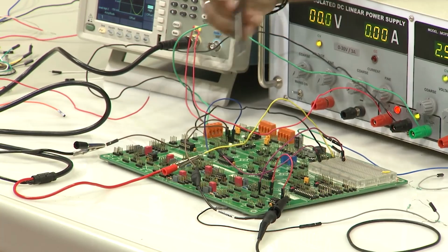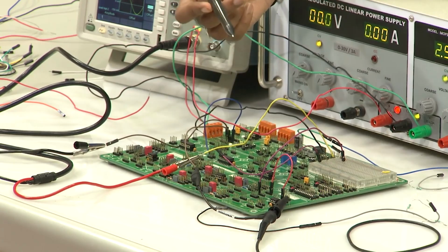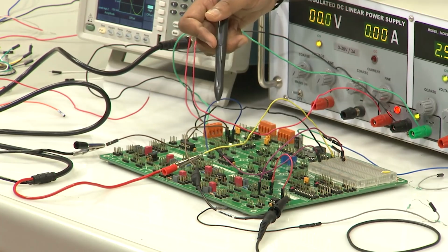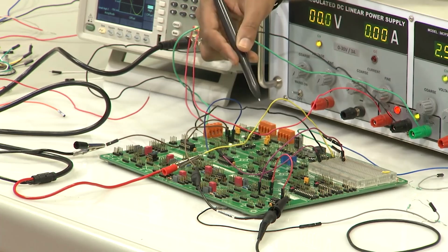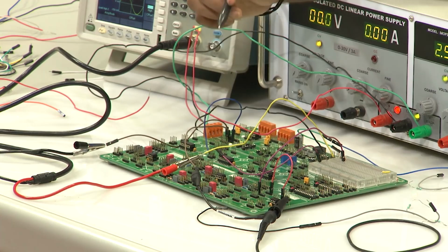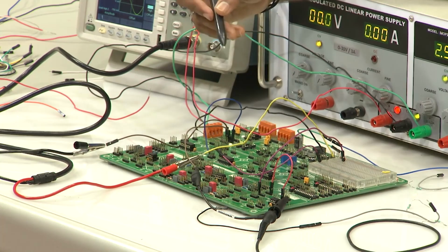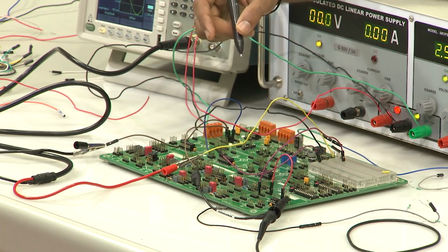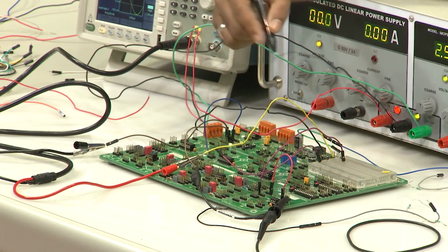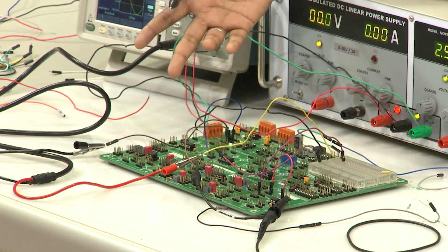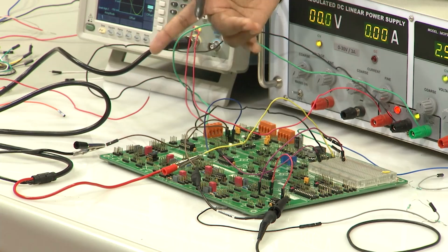For that we need to use the op amp in its non-inverting configuration. Why? Because from the circuit design point of view, we connect the output back to the input. We need negative feedback, right. If it is positive feedback, the output will simply saturate or oscillate. So, we connect the output back to the inverting input terminal. So, what is your R2 resistance then? Then your R2 resistance is 0. For R1 you can even give an input resistance, because that does not have an effect on the gain.